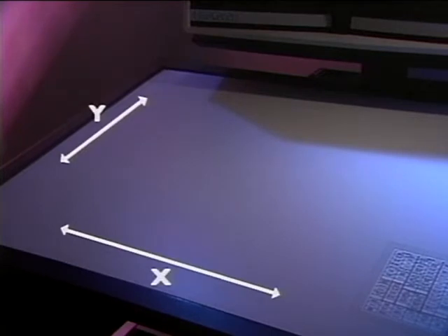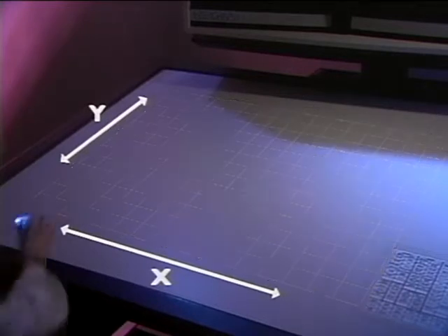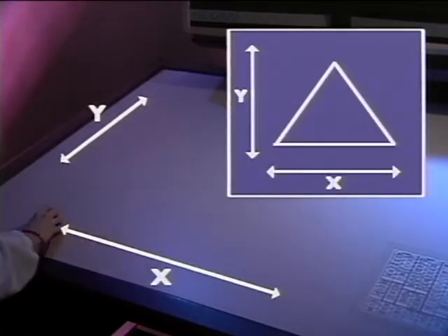The relative positions of cadastral or map features are accommodated by defining all positions in terms of a plane coordinate or XY grid system. The map features are positioned in relation to geodetic survey control points, which can be expressed in terms of plane coordinates. 2 or 3 control points per source document are sufficient to determine the orientation of the plane coordinate grid in relation to the map.